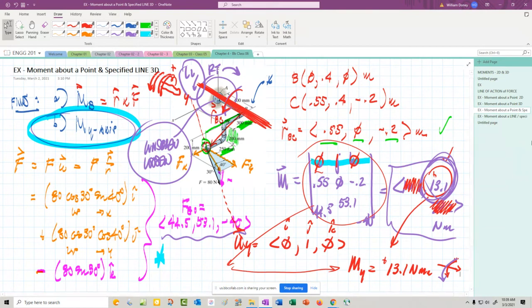So maybe, if this was some pipe assembly in the basement or something, we would have to have something that comes up here and connects with the ceiling, some rod or wire that holds this thing up so it doesn't rotate down. Who knows? But again, that's for the designer. We're trying to just look through this to find out what the loads are.